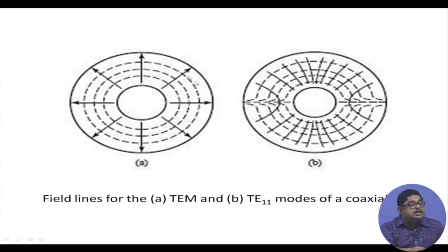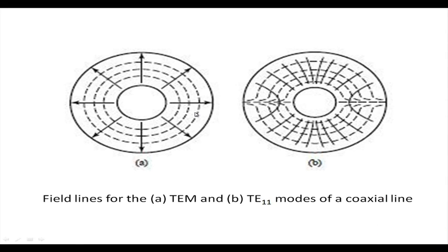So, that was the coaxial line. We have analyzed coax a lot. In the transmission line theory you have come across this, and here from the field theory viewpoint we have seen the same field structure. You have seen that in your earlier transmission line classes you derived this electric field and magnetic field, but from the voltage-current concept here also we came there and see that the electric field lines are like this, etc. So, we have demonstrated that the TEM mode theory whatever we have developed, if you apply it, you can calculate the fields as well as various parameters like characteristic impedance, etc.